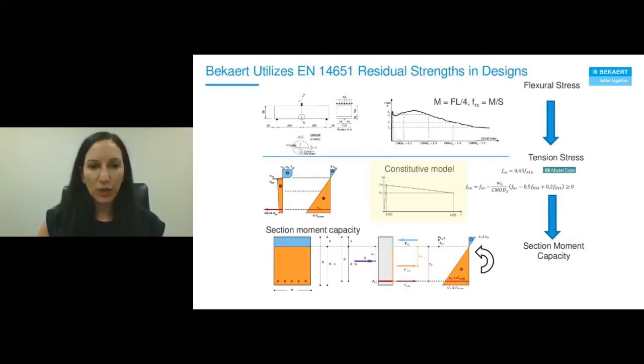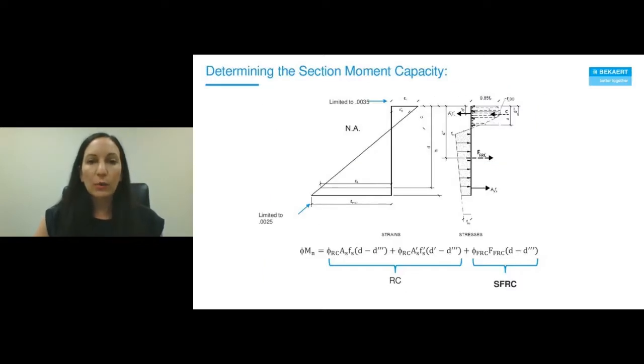that trapezoidal shape. So now, for those of you structural engineers on the line, when you think back to your stress strain diagram and establishing what is the section capacity, right? Now, in addition to whatever reinforcing might otherwise be present, now we have this trapezoidal stress contribution that the steel fiber reinforced concrete participates in tension south of the neutral axis.